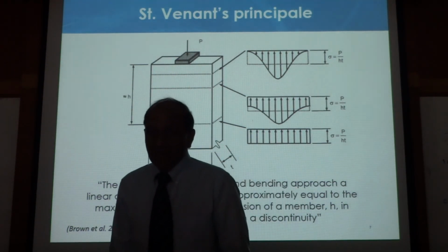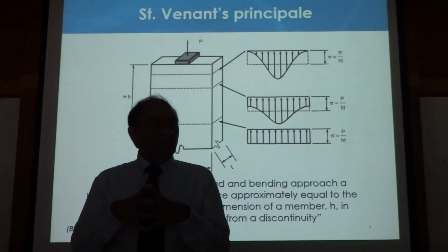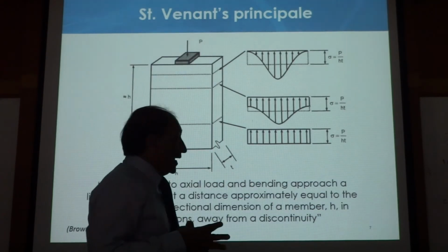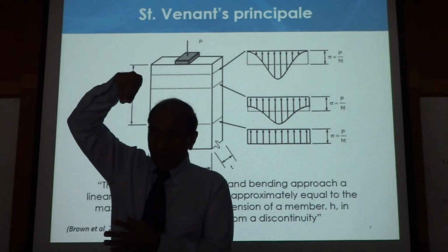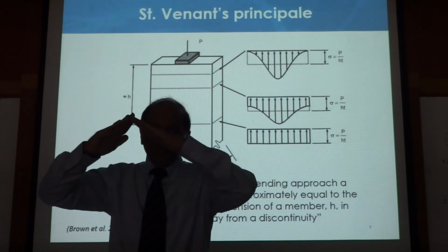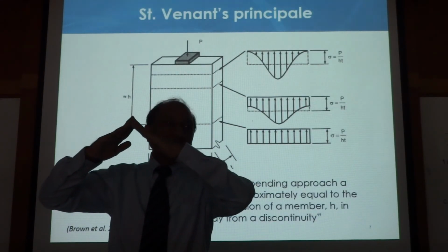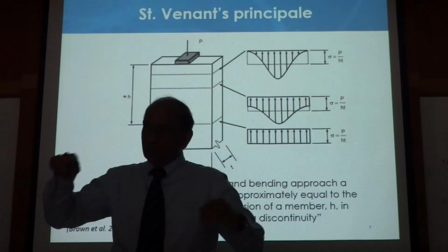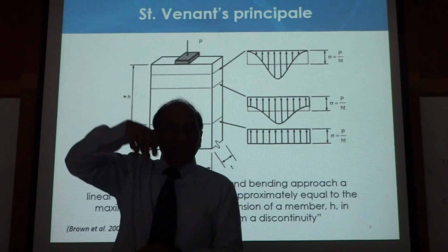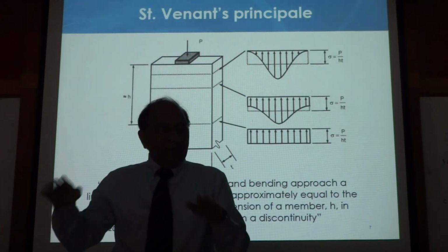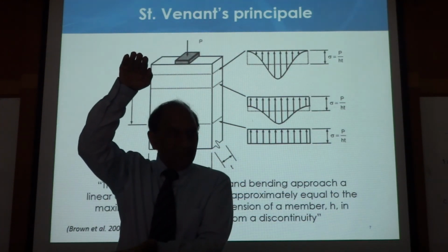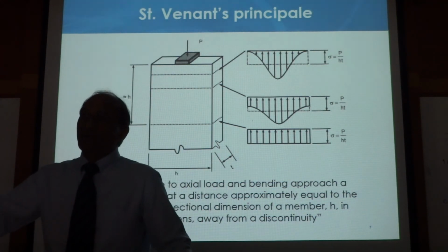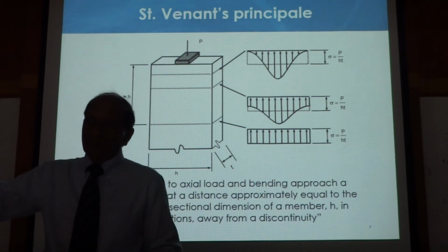In fact, when you design a masonry wall or a brick wall, right, and if you put a lot of load on the brick wall, there is a certain angle, you might have read about this or might have used it, after which the load becomes uniform on the wall. So the local effect of the point load can be converted into a UDL after a certain distance, right? By the time the point load reaches the foundation, it becomes a uniform load. So you can divide it by the length of the foundation.